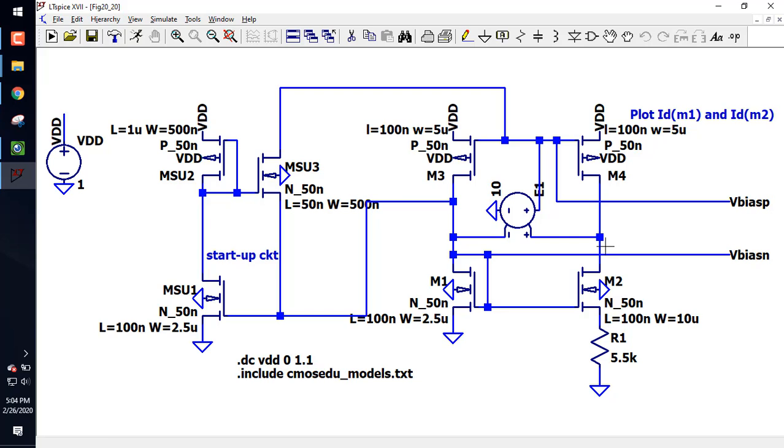Okay, next question. If that's the case and I need negative feedback, why did I tie this node to the plus terminal here instead of to the minus for negative feedback? When the gate goes up, the SP goes down. Yeah, when the gate goes up, this is acting like an inverting amplifier. It inverts the signal that I feed back, because if the gate goes up, it shuts this off and this goes down. So this inverts the signal that I put at the gate.